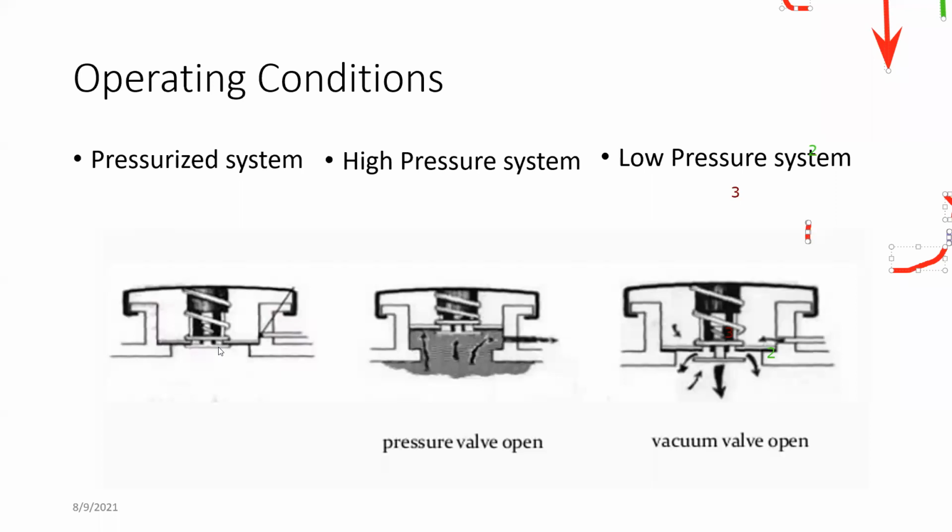Then after you drive for some time, the engine temperature rises and your RPM increases, and because of that, the pressure inside the coolant system is increased. As a result of that, now the pressure valve opens. Pressure valve means number two valve, so it can only move upwards. Once it is completely open, once it overcomes the pressure of this spring,